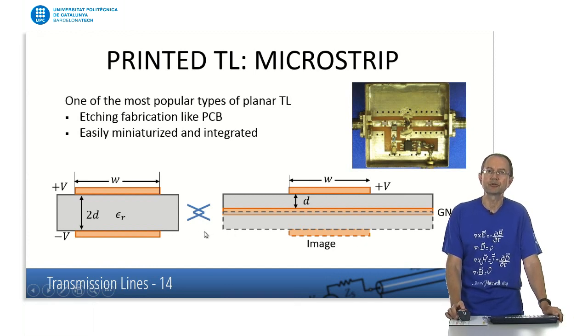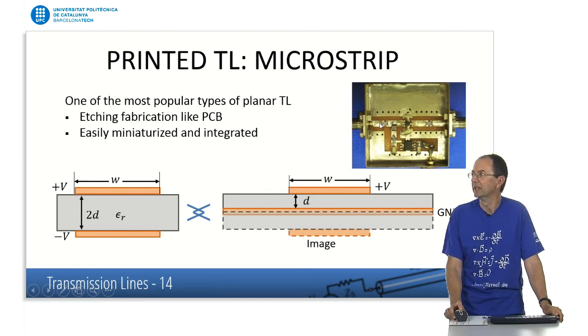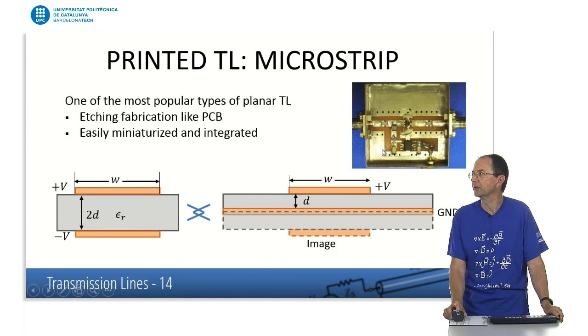So this microstrip line is just a printed line. You have here, for example, the input and the output of an amplifier, and this central strip is the active element of the microstrip. You have a grounded mass plane around, and also below you have a complete solid plate like this schematic shows.